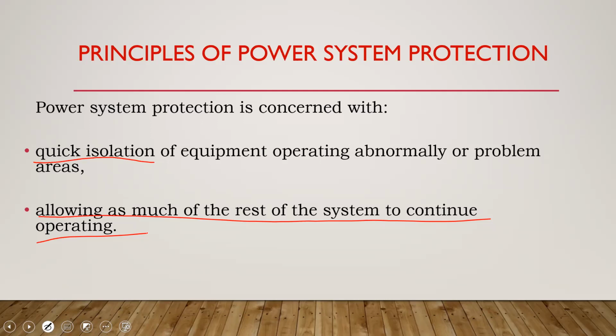The question is, if you end up with a fault, let's say you plugged in a faulty iron in the kitchen or wherever you do your ironing. You would not want your living room breaker, the breaker to your bedroom, all trip at the same time. You want just that single circuit that is controlling the kitchen to trip.